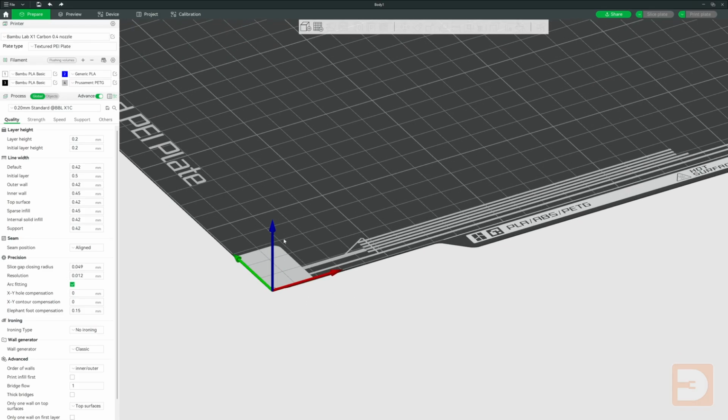In the Z axis, the resolution of your print is controlled by the layer height, but in the X and Y, whilst it will absolutely be affected by the nozzle size that you have fitted, you can further adjust the resolution of your print here.